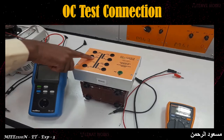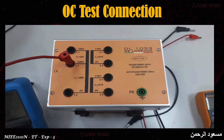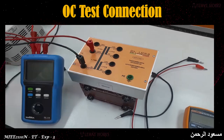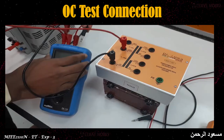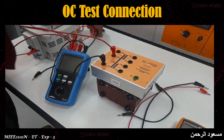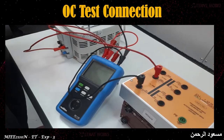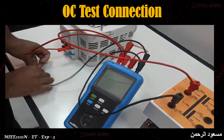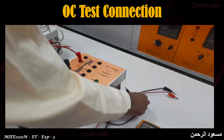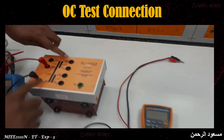And zero potential point, zero voltage point is connected with the V point of the wattmeter, and the V point of the wattmeter is connected to auto transformer's output side neutral point. Okay, so again I am saying this is the connection you have to follow for all the three tests, whether it is a load test or short circuit test or open circuit test.